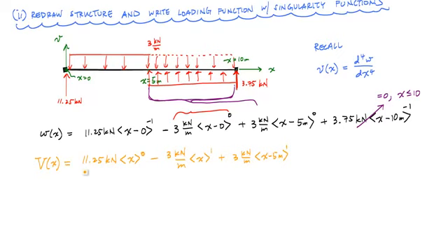And so here, if you plotted the shear function, you would actually get the shear diagram. And same thing here, if I integrate again, now I'm going to get the moment diagram, or the moment function. So here's my moment function, and I want to emphasize here that we started with the loading function, but really we could have just started from here.